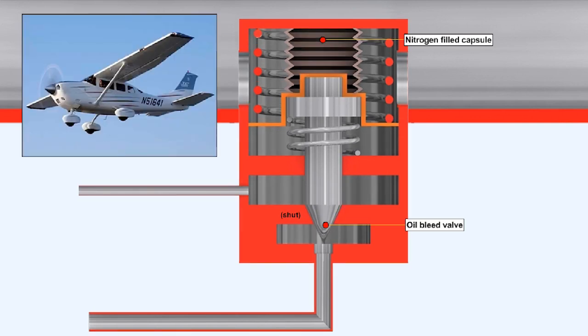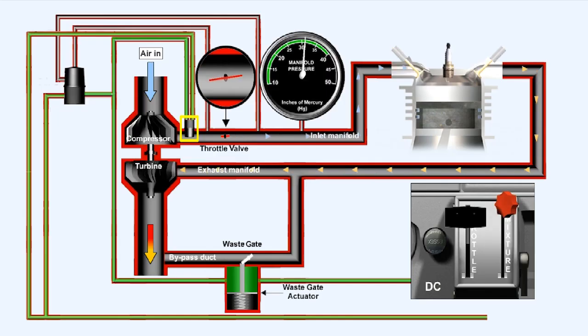Having a density controller will ensure that maximum available density will increase up to critical altitude. By so doing, the density controller will reduce the losses normally associated with charge temperature increase, and thus density decrease, which would otherwise occur as the aircraft climbs. Either the density controller or the differential pressure controller will be in use and controlling the wastegate position at any one moment.